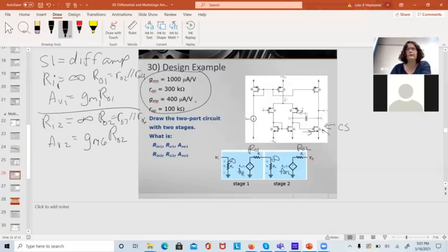And yeah, I've been putting that on the exam for like 2 or 3 years. Maybe I'd give you those values and I just tell you to put it into a 2 or 3 stage model of an amplifier. But that's really the big picture that everyone needs to know out of this, not just the IC designers, is being able to look at a circuit or an op-amp, figure out its output resistance.